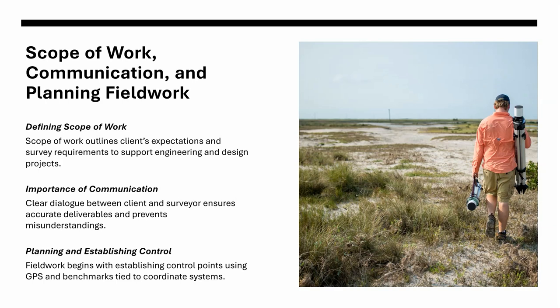Must the drawing be tied into state plane coordinates or into a local grid? Should elevations be NAVD 88 or is another vertical datum preferable? If these questions are not clarified up front, misunderstandings can occur. The drafter must be aware of these expectations because they shape how the survey is processed, drafted, and delivered.